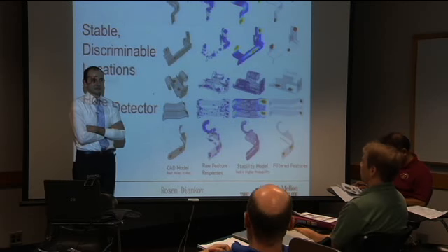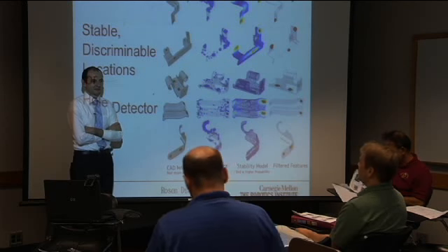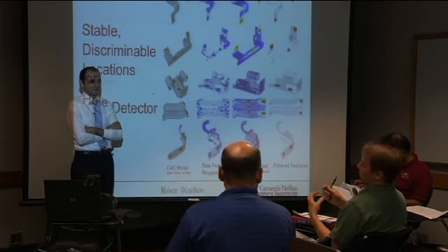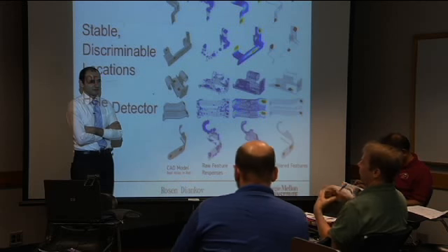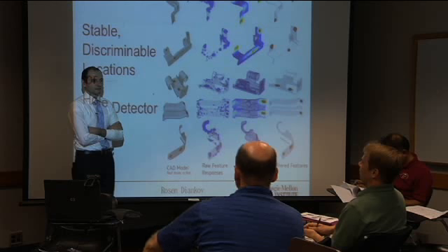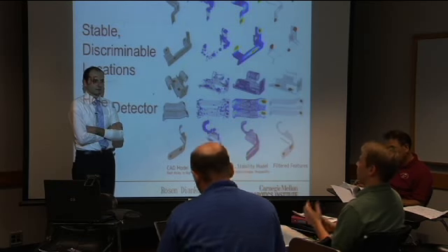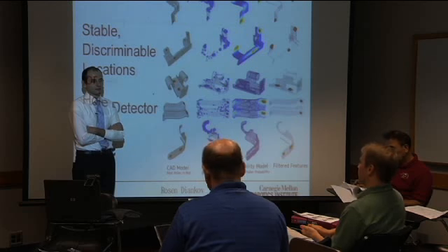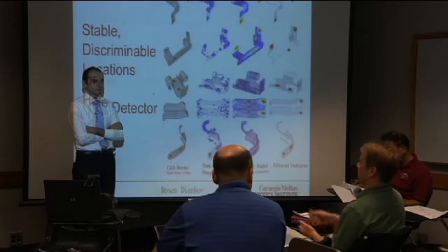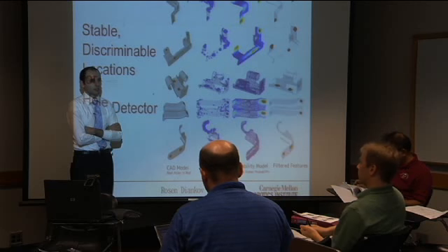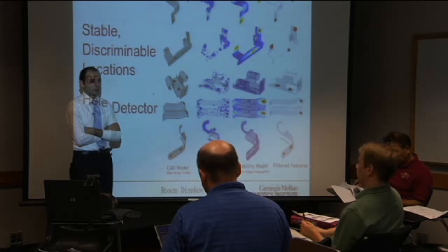I was actually expecting you to say something about the tasks that you're looking at. Like, for me, pick and place tasks. If you're not trying to do two-handed assembly, right, or something that requires managing internal forces, you can get away with a lot of these kinematic and geometric approximation tools. I think if you are doing insertion of a peg in a hole, or something that requires force feedback that is quite vital to the success, then it might be more important.